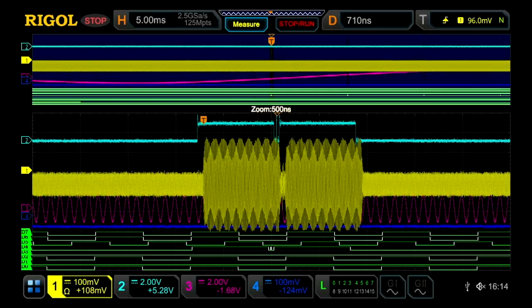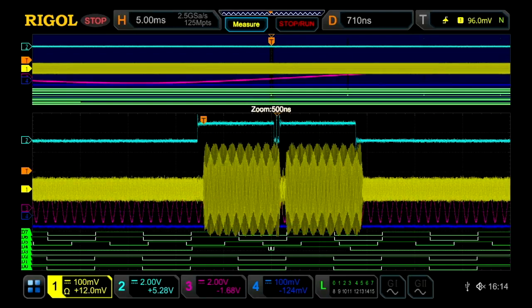We can even identify some other signals like channel 2 in blue and D4 down at the bottom that appear to be related to this pulse activity and the glitch in the middle of this pulse. So this mode really allows us to see the same full 50 milliseconds of time with 5x oversampling on all our channels, but capture the signal in context and use the memory in a more flexible way to get all the information we need.